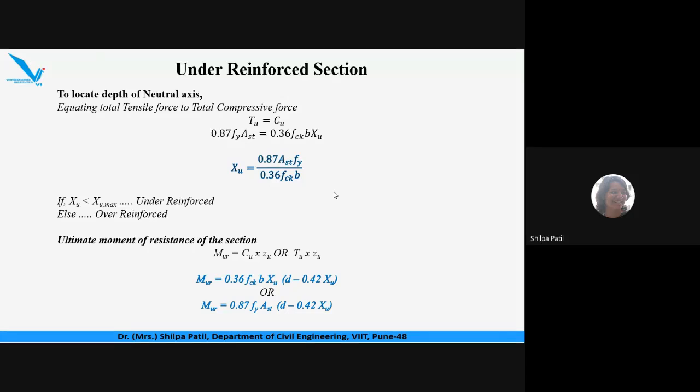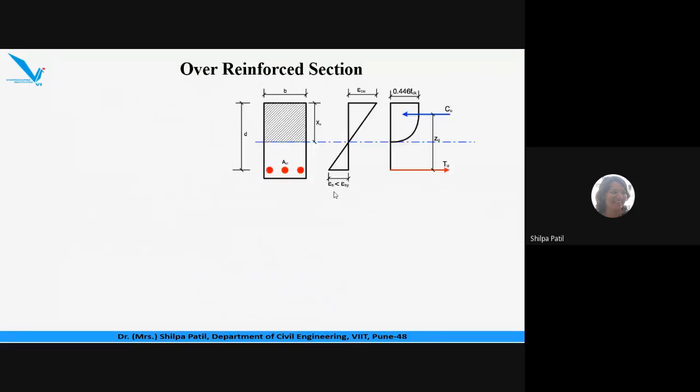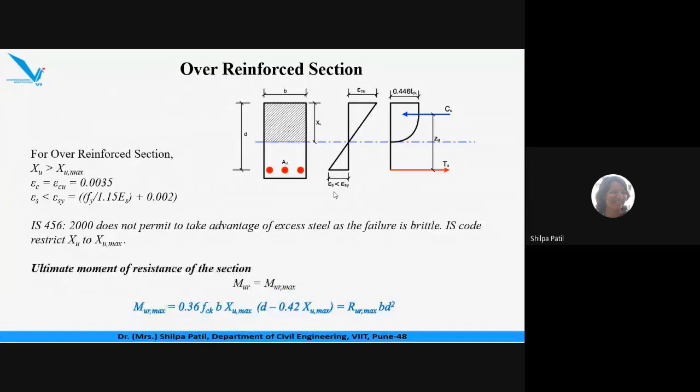So the fck value we also know. Both these formulas, or either of these formulas, are applicable for an under reinforced section. This does not happen in the case of an over reinforced section, because there the failure is due to the failure of concrete first. The strain developed in the steel is not equal to the strain corresponding to yielding, and hence the stress is also not equal to the yielding stress, that is the Fy value.